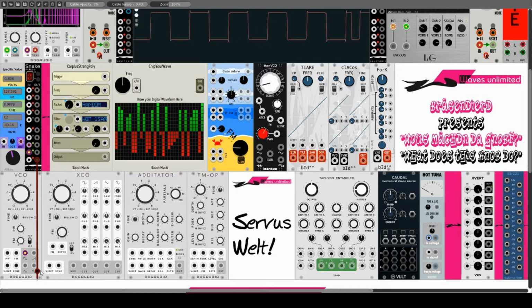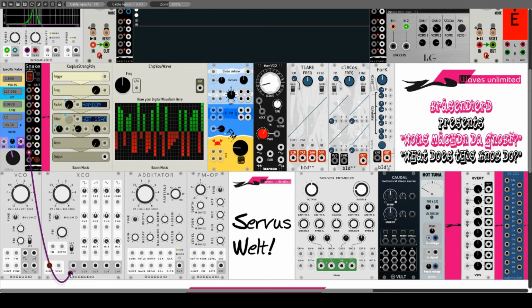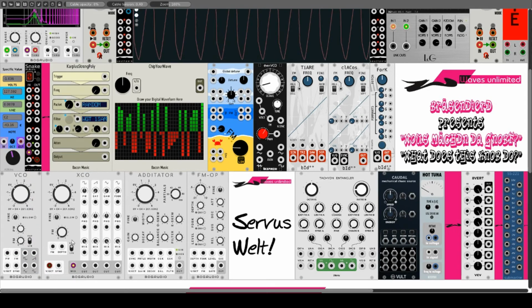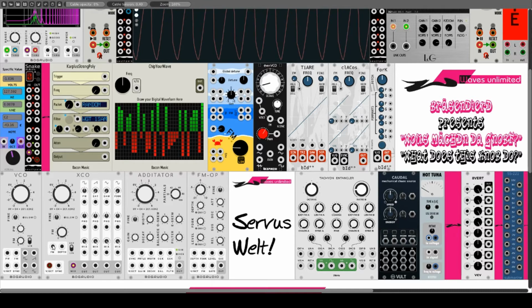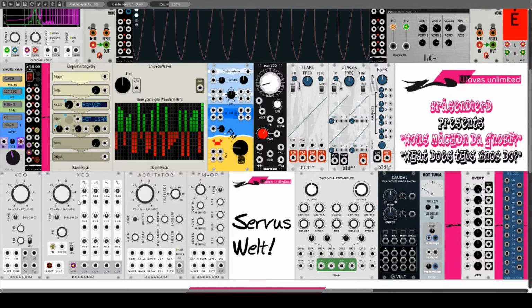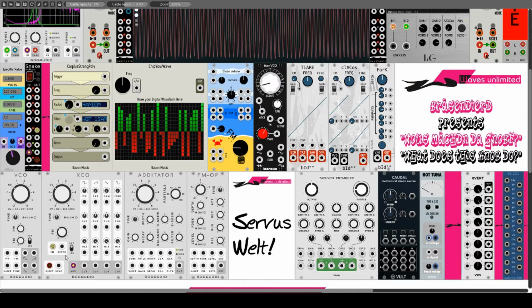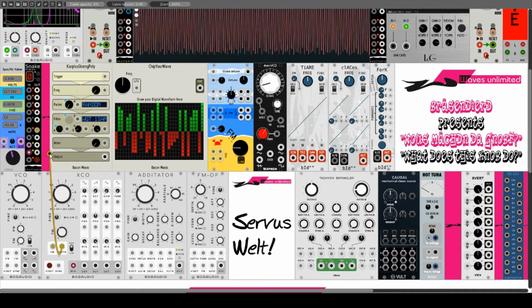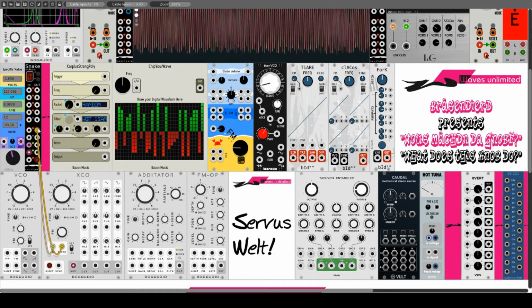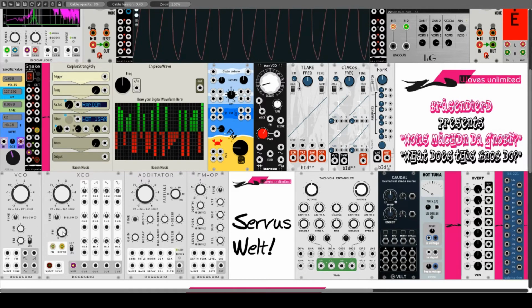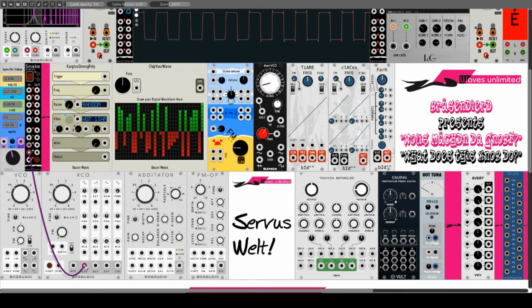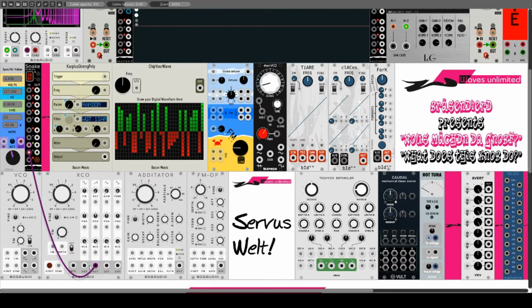XCO could be considered the big brother. It has everything VCO has. In addition, it has a CV input for the modulation depth of the frequency modulation and offers the possibility to influence the waveforms individually and output both as a single and as a mix signal.